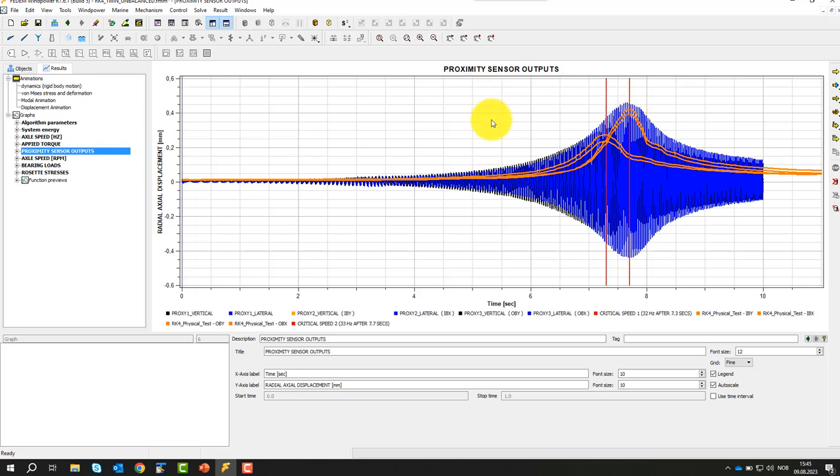The reason is probably that I have a model which is not fully representing the physical model. It might be that the physical model is not clamped as it should be. It might be that the sideways stiffness is too low, indicated by the first peak here, and that the vertical oscillation or eigenfrequency of the real system is a bit higher than the horizontal eigenfrequency.